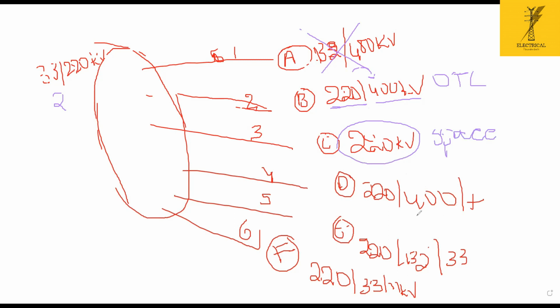But here, the 400 kV lines are highly loaded. If one of the lines fails, at that time, I have to shut down my system. The other line cannot carry much of the power. So the line loadabilities I am checking. And so I went to the next substation. Here in this substation, I have checked all the conditions are satisfied, but the existing fault level in the 220 kV is already 38 kA. When I am coming and integrating to this substation, the fault level from my substation is contributing. If a fault occurred in the substation, the generators from my side are also contributing to the fault, which is suppose a 6 kA, which is crossing the limit of 40 kA. So I avoided this also.